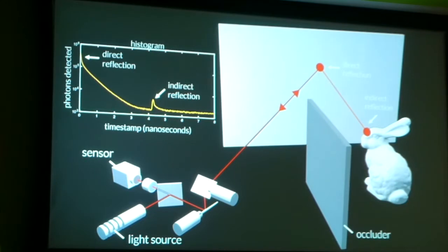And if you are doing this with a SPAD, these are the types of measurements that you'd expect. So this is a histogram of the number of photons that we detect over time. I've arranged this so that time 0 is the time at which we're detecting photons that are hitting the wall. So of course we get a lot more photons from the wall than we would get from the hidden object. That's the peak that arrives a few nanoseconds later, just because as light is scattering out, we're actually losing quite a bit of signal. And this is also why SPADs are really helpful. They give us both the time resolution, but also the sensitivity to detect these very weak signals from the multiply scattered light.